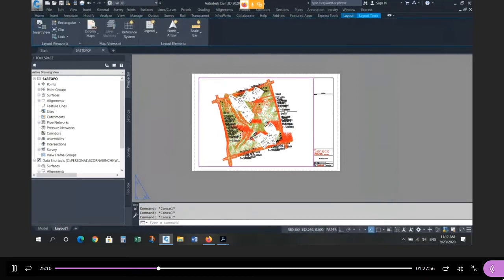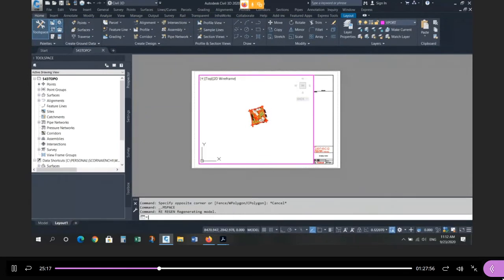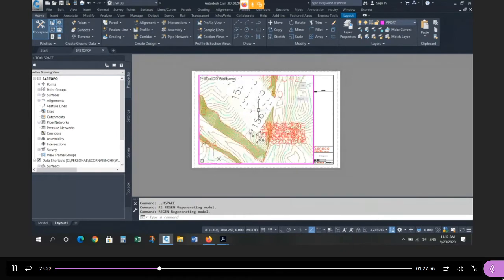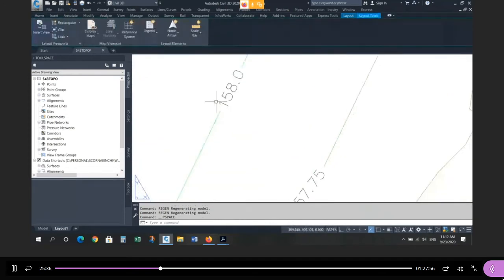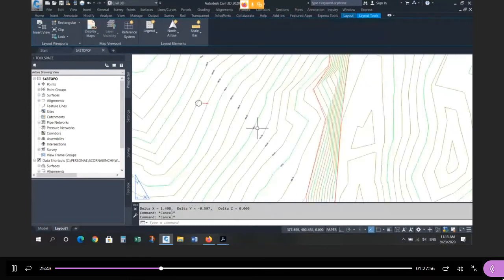Now to prevent that from happening, and notice when the object gets smaller in paperspace, if I regenerate, regen, the items would get bigger. If I zoom in, the object gets bigger, I regen, everything has to get smaller. So it's always trying to compensate. It's always trying to keep a constant text height. It's annotative, okay? If you zoom in on here and you measure in paperspace, it should be about 2 millimeters high. Okay, in this case, 1.5 millimeters high, right?